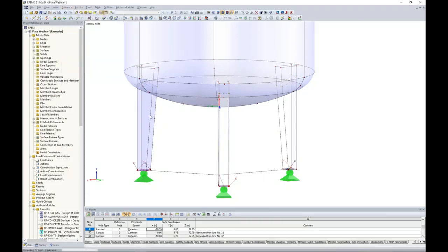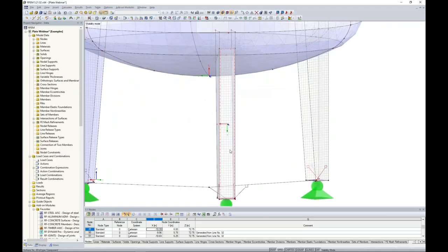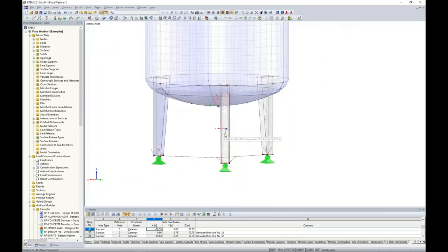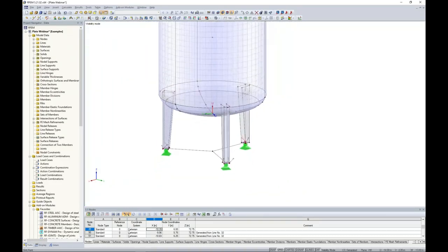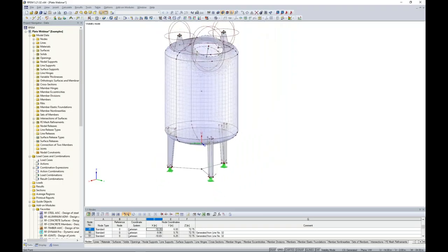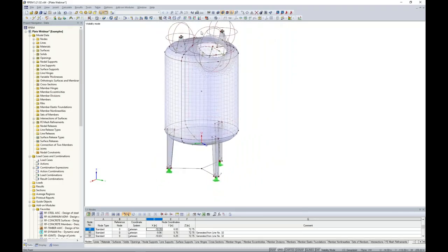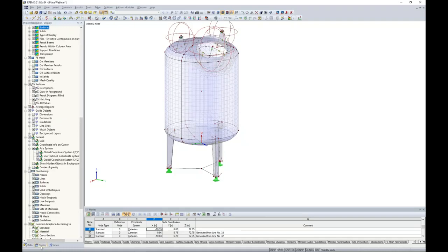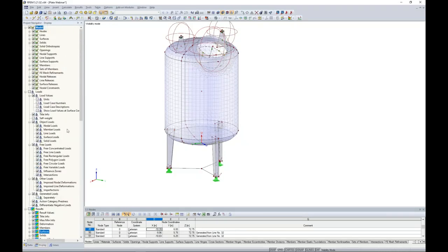I go to Calculate, Generate FE mesh. And now we can see that this FE mesh looks considerably better. It transitions quite nicely, again, back to that 2-inch length set for our global settings. Now, these FE mesh refinement symbols under the Display tab all the way up at the top, we can always turn them off. So they're still occurring in the background, but maybe they're just kind of getting in our way when we're modeling. We can just simply turn them on or off with this option up at the top.